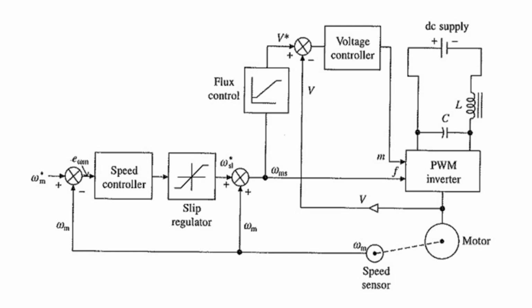Second point is the drive performance. Any non-linearities which are present in the converter motor system, the inner current loop reduces their effect. So the second major advantage is that the inner current loop is useful for reducing the effect on drive performance of any non-linearities present in the converter motor system. So that's why we are choosing an inner current loop and an outer speed control loop.